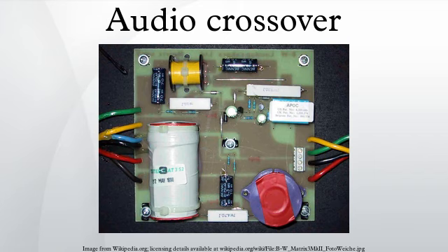Signal crossovers allow the audio signal to be split into bands that are processed separately before they are mixed together again. Some examples are multi-band dynamics, multi-band distortion, bass enhancement, high-frequency exciters, and noise reduction such as Dolby noise reduction.